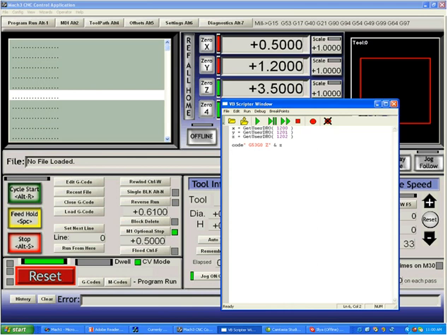Now, what can be important in some programs is that you delay further statements until a previous statement is done. It's not always necessary, and let's try it without it first. We'll do a code, G53. We're already in G0 because G0 is a modal command, and we put a G0 on the previous line. So in this case, we can put X, quote, ampersand X, ampersand, quote, put a Y, ampersand Y. Actually, we don't need any more ampersands. That's it. So the line that we're going to execute is G53 X and whatever X is, Y and whatever Y is. Now we can test that to see if we're happy with it.